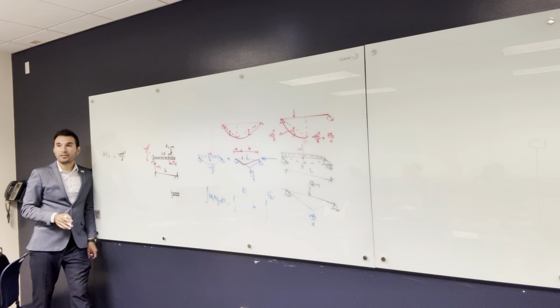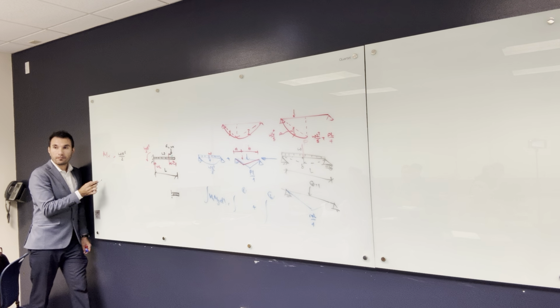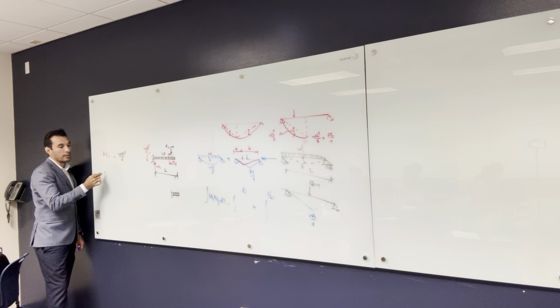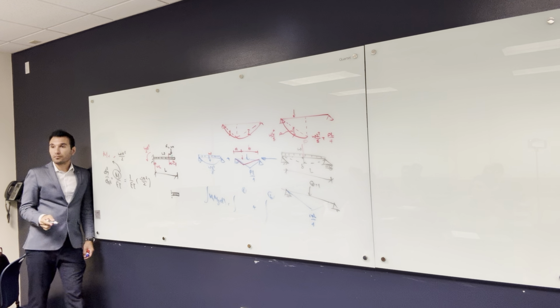Alright, so what is the double integration method is, like you guys remind me. So we have the slope, it will be slope is equal to integration of. Yeah, so you have d squared y over dx squared equal to M over EI, right? Yeah. So the thing is, we need to find this, and that's what we did here. So d squared y over dx squared, we're gonna have 1 over EI multiplied by WX squared over 2. That's a very simple problem.